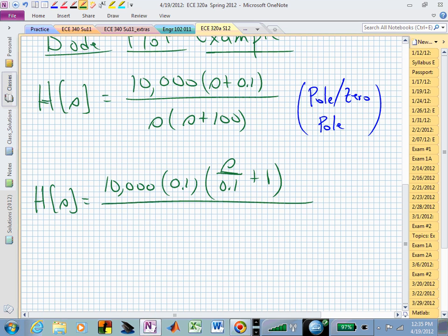What's the time constant of that factor? 10, right? It's tau s, where tau is what multiplies or scales the s, and tau is 1 over 1/10, or 10. Then we have our pole at the origin, and we have our other pole at 100, and we have then a real pole and a real zero. We have a pole at the origin, and we have a gain term.